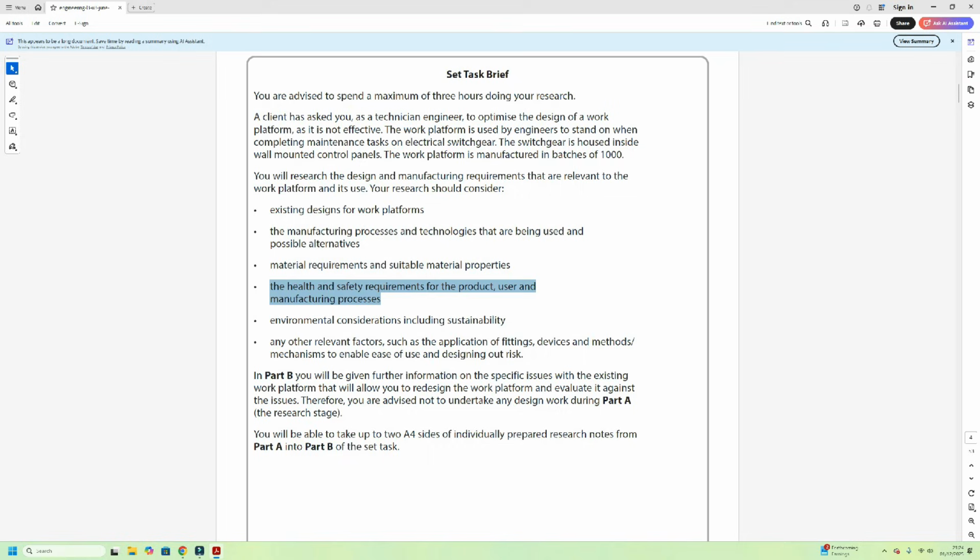A manufacturing process, so CNC equipment, obviously your employees need to be trained on it. At the same time, if you're using the bending equipment, you've got to be careful that they don't catch their hands on it, so you'll have all the safety barriers. The folding equipment normally has a light barrier. If you break a light barrier, it should stop the machine straight away.